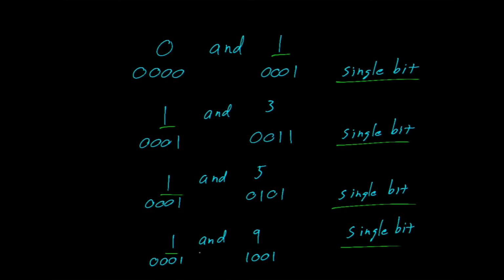Suppose you had a circuit that responded to minterm 0 and 1. Now, we could certainly build that as 2 4-input AND gates, but it would be nicer if we could somehow combine the terms. And we can. If the circuit responds to both minterm 0 and 1, you could describe the circuit as a 3-input AND gate, as D0, C0, B0, with no sensitivity to A.